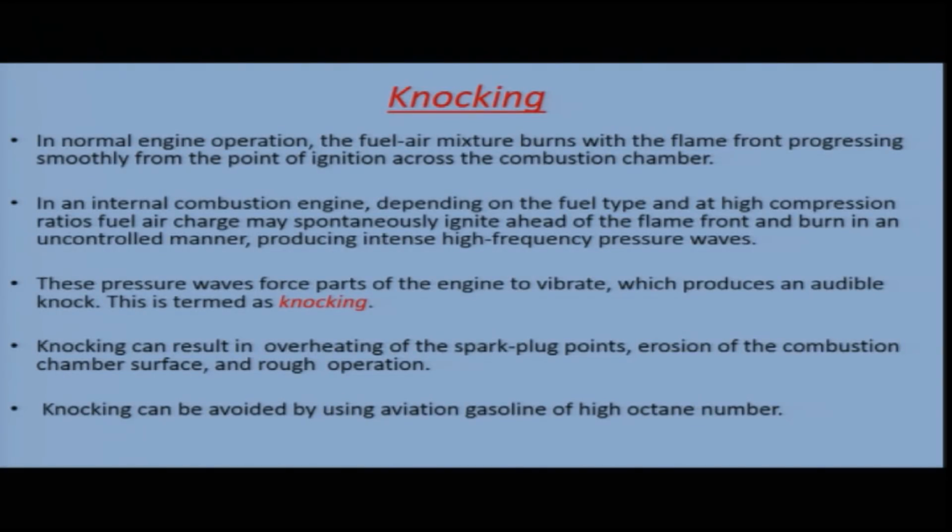Now, what is knocking? We have seen in our previous slide that aviation gasoline is rated in terms of octane number, and high octane number fuel is required. So, let us see what is knocking, because high octane number fuel is required as it has anti-knocking qualities, anti-knocking properties. In normal engine operation, the fuel air mixture burns with the flame front progressing smoothly from the point of ignition across the combustion chamber. So, in normal operation, the fuel burns smoothly, the flame front progresses smoothly from the ignition point and all across the combustion chamber. So, this is your normal operation.